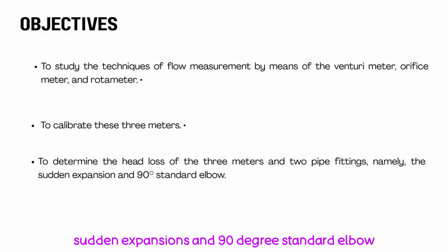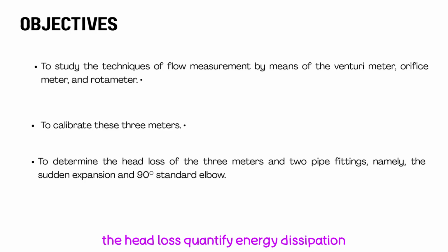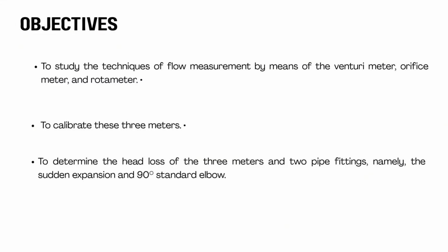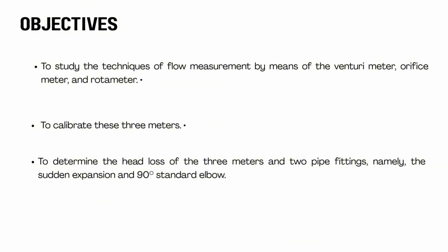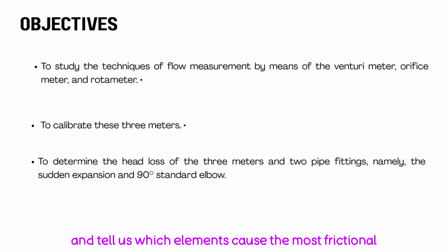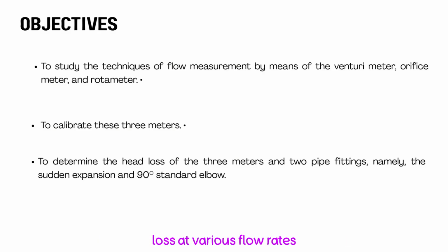and a 90-degree standard elbow. The head loss quantifies energy dissipation due to flow contractions and fittings. Understanding head loss helps in system design, pump sizing, and energy budgets, and tells us which elements cause the most frictional loss at various flow rates.